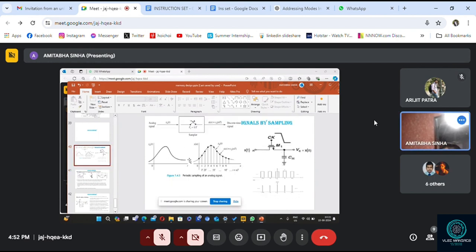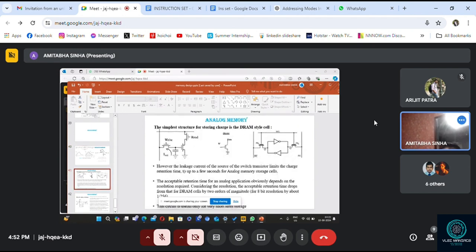Once again, this is a continuous signal. The continuous signal comes to this sample and hold circuit, and it is held in the CH register. This capacitor holds the data. If this data has to be written, it will be connected to this read-write circuit. If you want to write the data, that data will be presented over here and stored in the capacitor. And if you want to read the data, it can be read directly on the horizontal line. So that is the simple one-sample storage device.